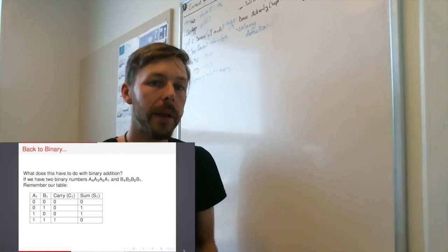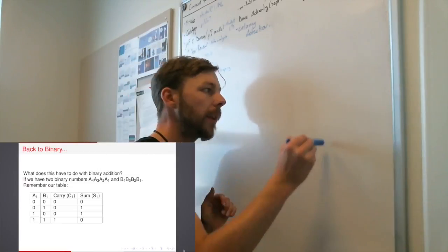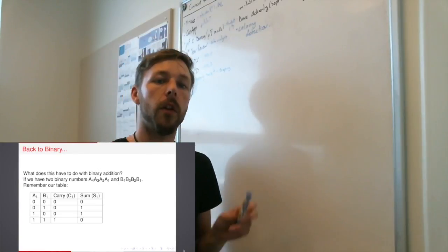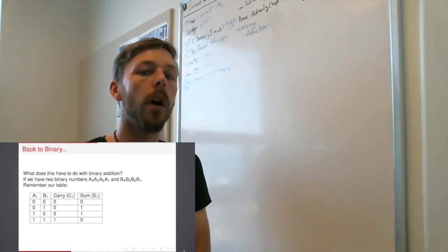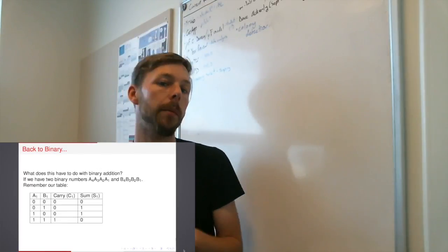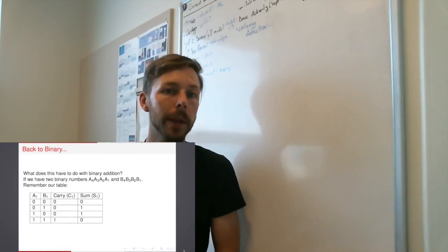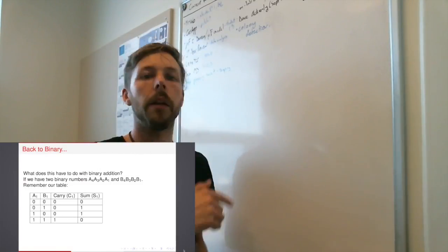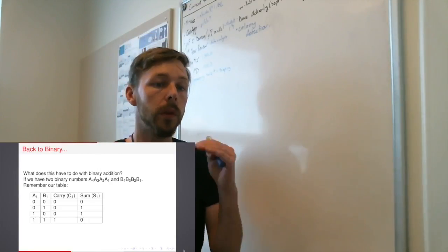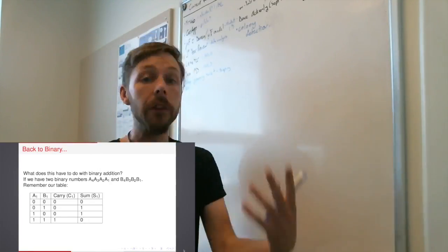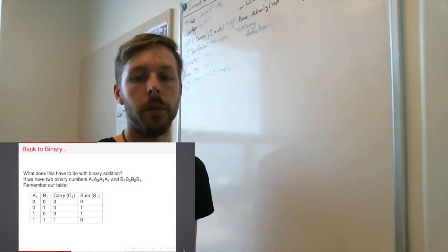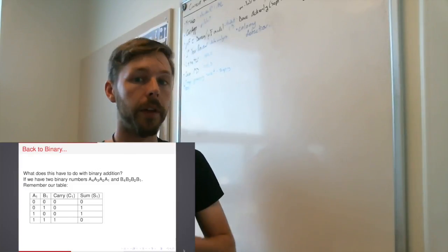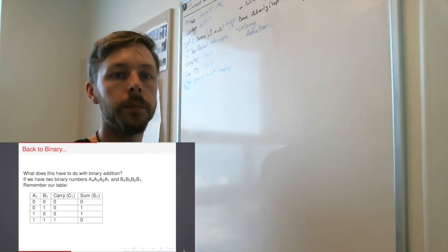So what that practically means is, without doing the bitwise binary addition that we did by hand before, just by using the logical operations of AND and exclusive OR, I can tell you what the carry and the sum bits of any binary addition process will be. And so physically that's how computers do it. They don't do this bitwise carry one add it process that we do. They do logical operations instead, and the end result is identical to decimal addition. So, summary, AND gates give us the carry outputs, and exclusive OR gates give us the sum outputs.